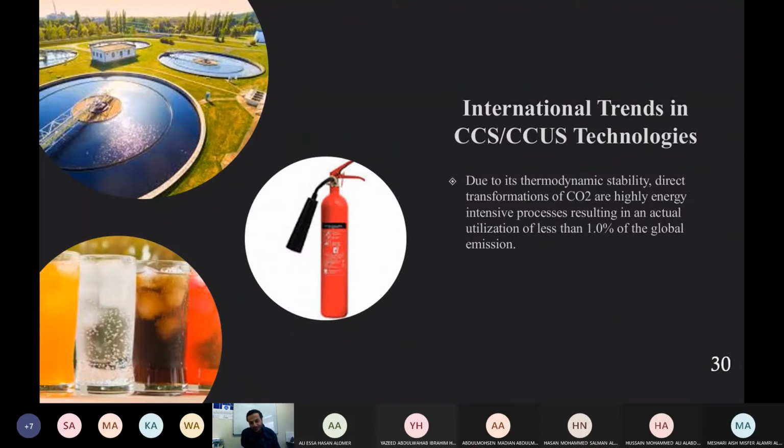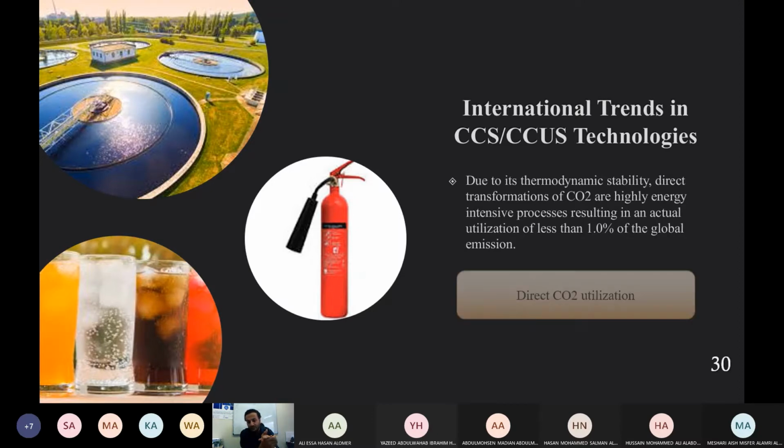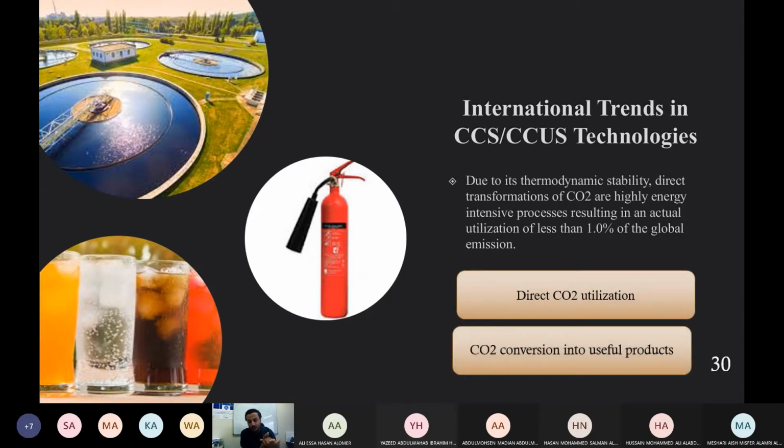For carbon capture technologies, we said we have oxy-combustion, and we have pre-combustion capture, in which we capture carbon dioxide before the combustion process through, as we said, the reduction of heavy hydrocarbon to lower hydrocarbon. Then we can separate carbon dioxide. We have syngas like CO plus H2.